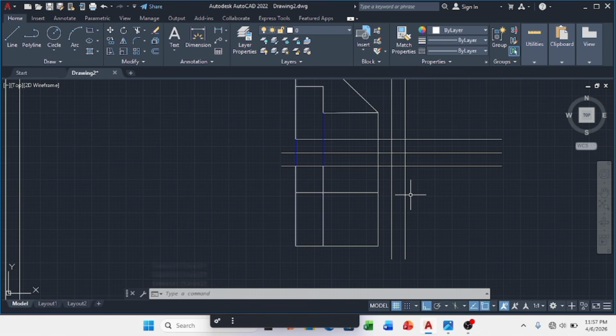So let's turn off the auto mode. Then let's come here and choose hidden. Then let's go to lines. Then from the middle here, we left click. Then we draw 45. So moving it, you see the angles too are changing. So 45. Then you left click. You click on escape. So you project the line to meet this 45.